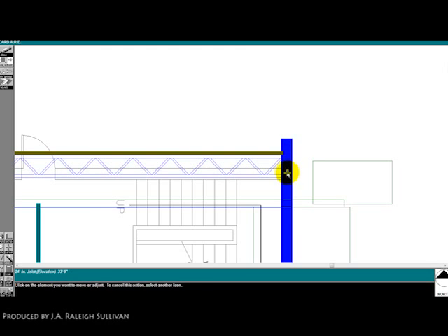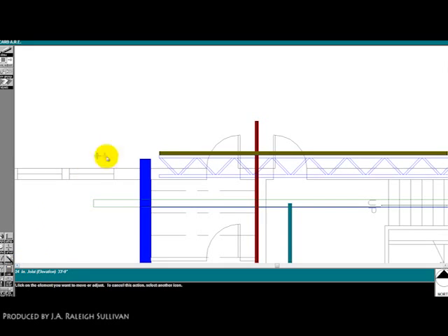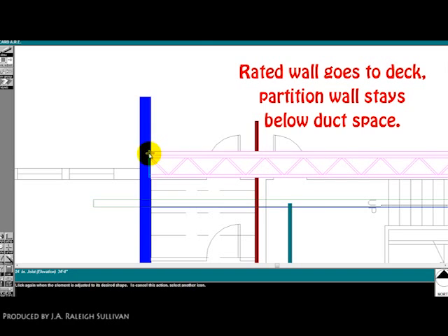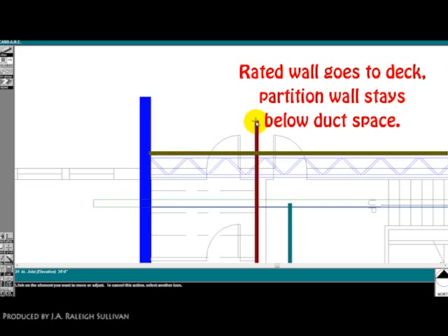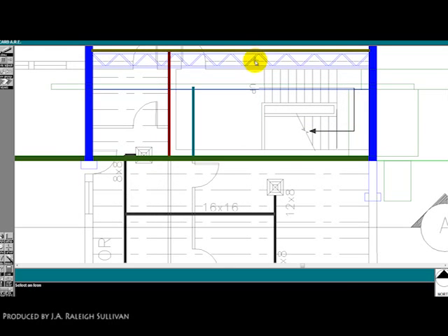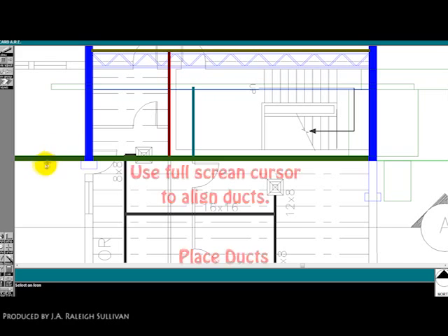Now I'm going to move the joist over a little bit so that it's clearly bearing on the bearing wall. You don't have to make it do this, taking it in 1-2 clicks, but this way I'm sure that it really is bearing. If you just leave the joist kind of touching the wall, you run the risk that it doesn't touch the wall, and if it doesn't touch the wall, it's structurally unsound and you'll fail.